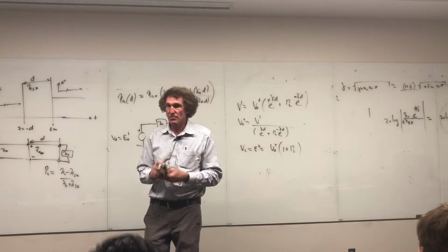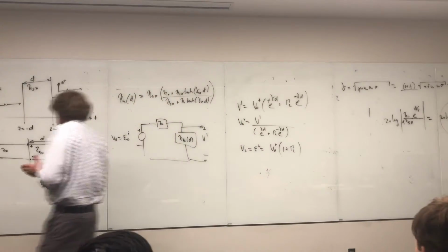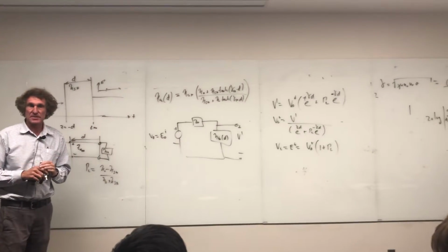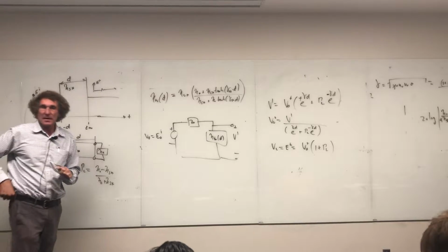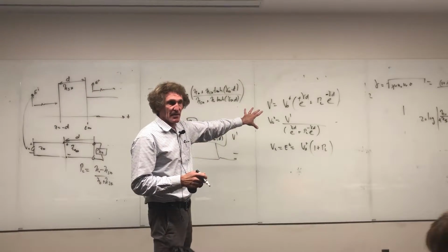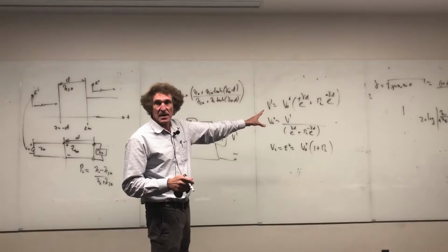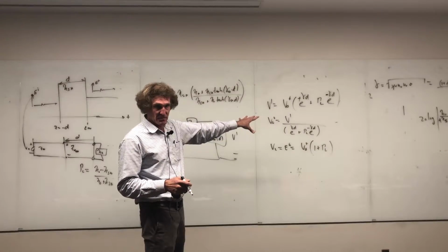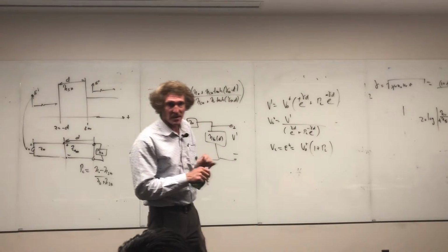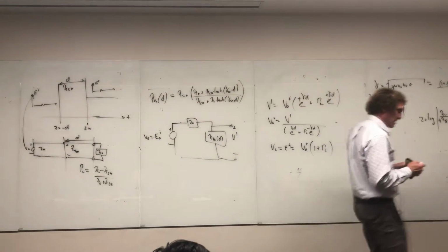That's how you do a shield problem in the frequency domain. If it's thin and there's a possibility of a lot of bouncing, that'll get you the right answer. If you ever make a shield, hopefully you never have to analyze it that way. That's the pain, and frankly, it's unnecessary. Just make the shield thicker, unless there's some ridiculous reason why you can't.